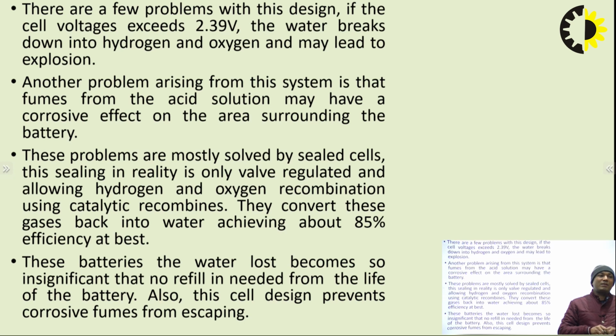They convert these gases back into water, achieving about 85% efficiency at best. Means you just pressurize hydrogen and oxygen and convert H2 and O2 again into H2O. So we will not have to fill the battery again and again with water.